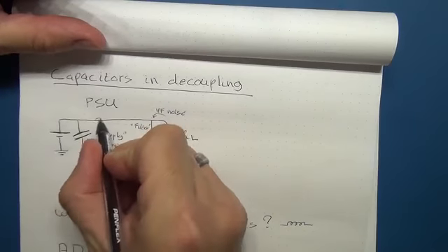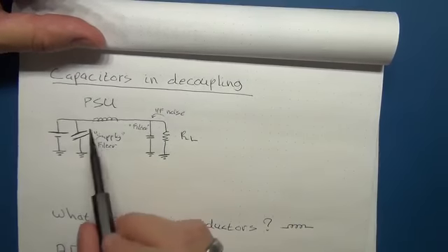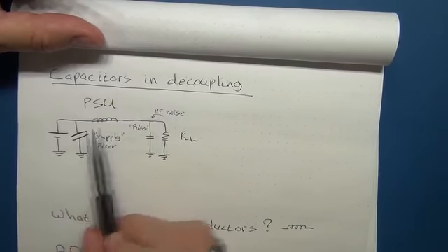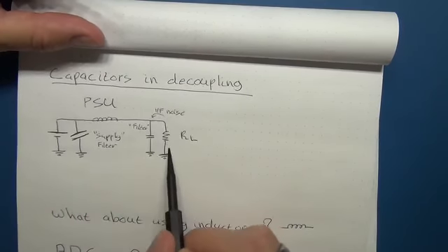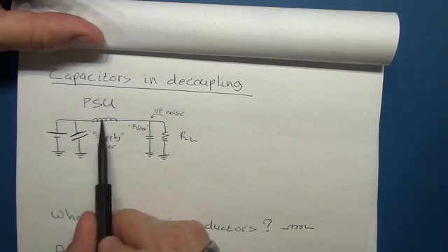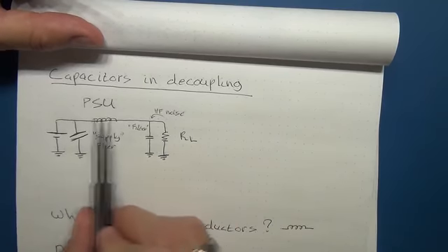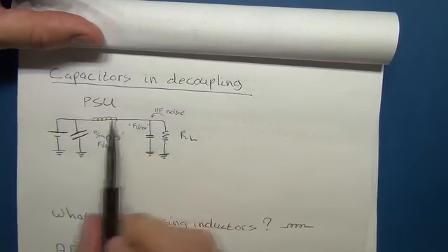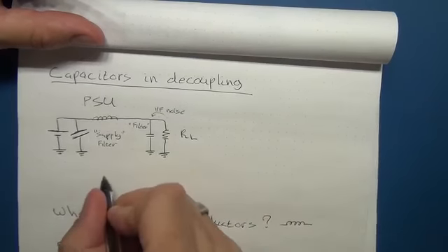What if we had to add an inductor to the circuit over there? Now some of you might recognize this straight away, but an inductor does the opposite to what a capacitor does. Let's say again we really wanted good sensitive noise filtering in the circuit to protect our load over here. Well, if we had noise coming out over here, an inductor resists noise. So it will resist the AC component, so it'll block it from going along here, whereas obviously the capacitor is doing the opposite. So that's why it's in series over here, and this becomes a pi filter.